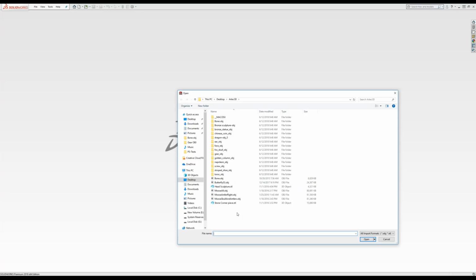And the second question is, what are the continuity conditions between the quads produced? I think I know the answer to that question, and the answer is that everything is G2. So it's curvature continuous. Unless you go in there and actually try and change it by putting a crease edge in or something, it's going to be automatically G2 continuous.